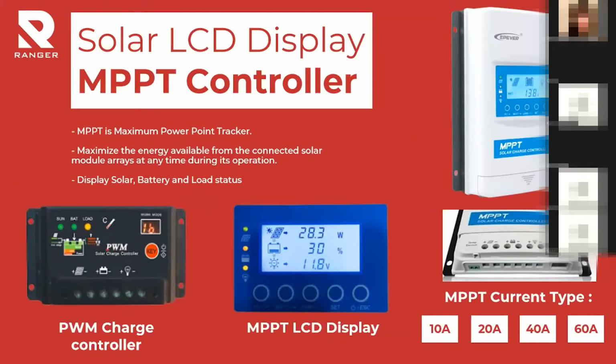Next is the solar LCD display MPPT controller. This MPPT controller is different from the normal controller, for example PWM versus MPPT. The difference is that MPPT is able to capture the excess module voltage to charge the batteries. As a result, MPPT can produce 20% to 25% more charging than a PWM charge controller.